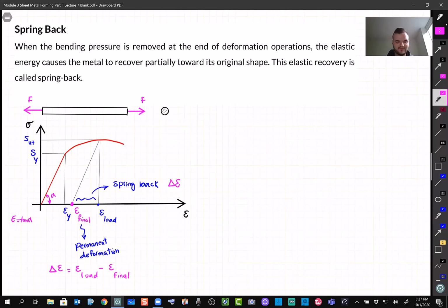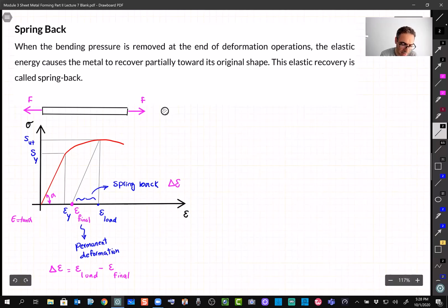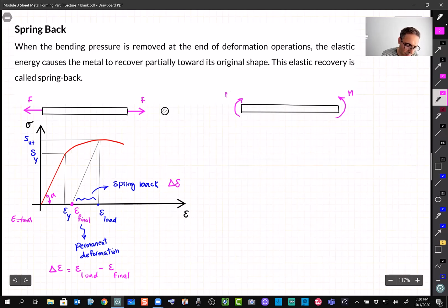All right, good. So now let's make it something relevant to what we want to discuss, which is bending, right? Let's say we have, maybe for simplicity, a beam. And this beam, this time, instead of tension, is under bending M. And let's say the cross section of this beam is, maybe for simplicity, just a rectangular shape, right?